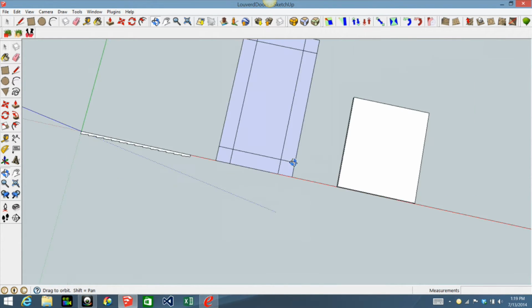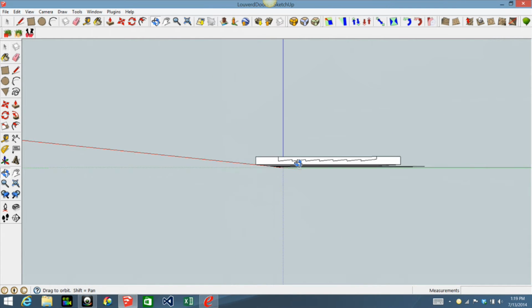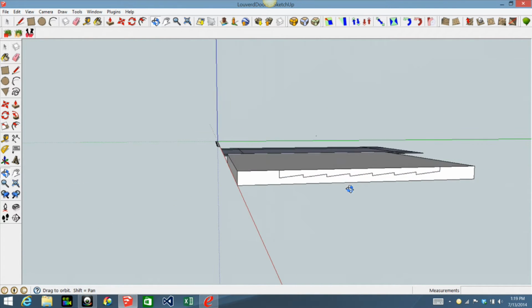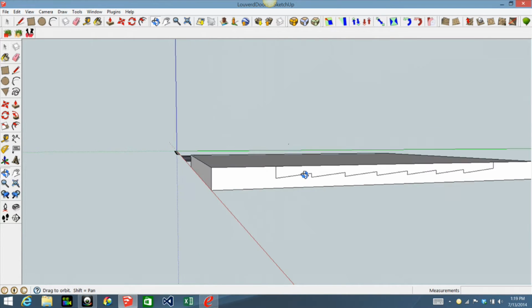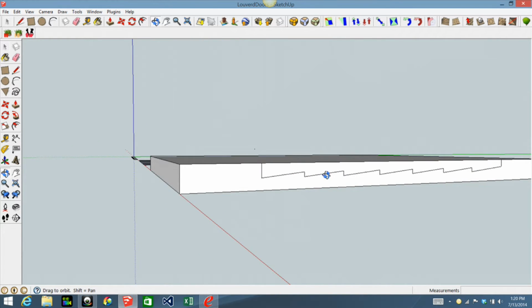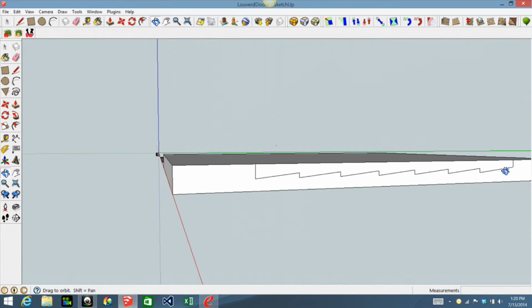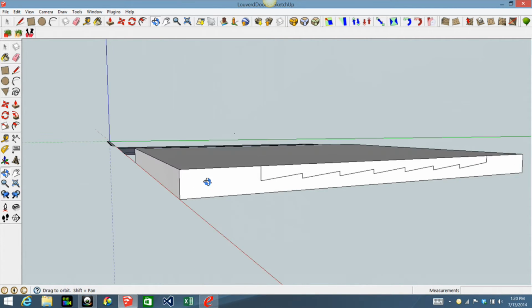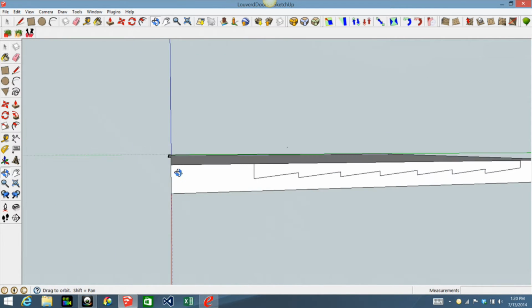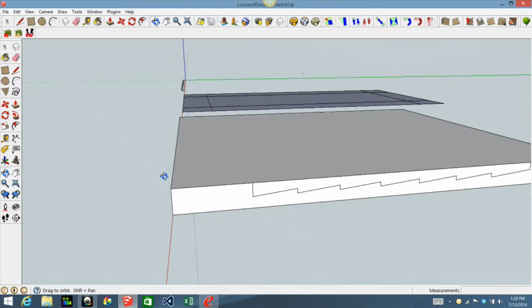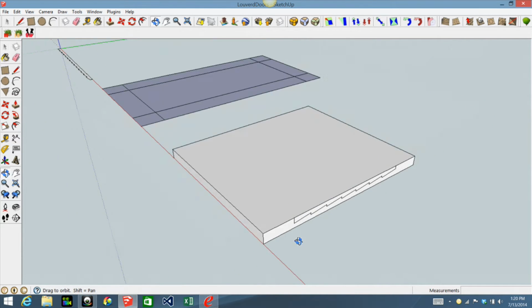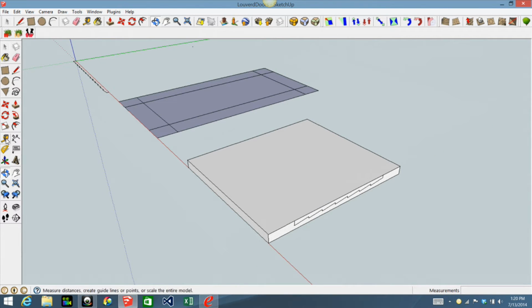What I've done earlier was I was doing a test to see if this would actually work and what all I would have to do. Got this profile here drawn on a 3/4 inch cube that I created, but it's not long enough. It needs to be 17 3/4. I'm using 2¼ inch rails and stiles, so in between here is 17 3/4.